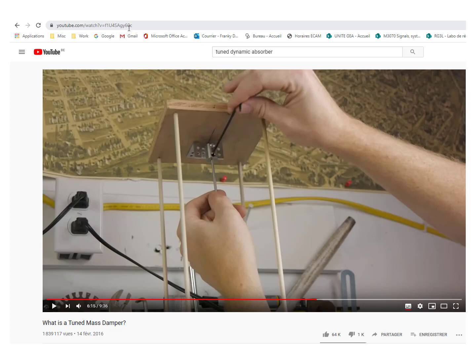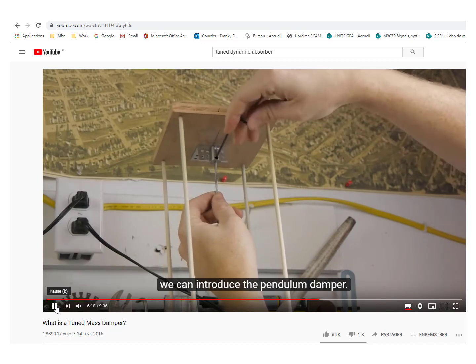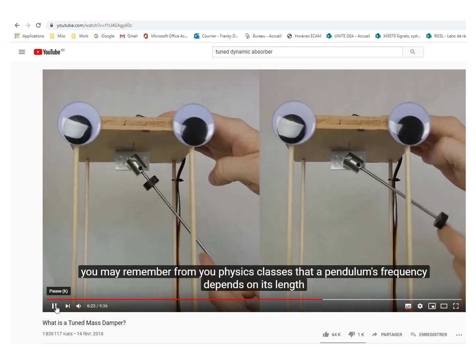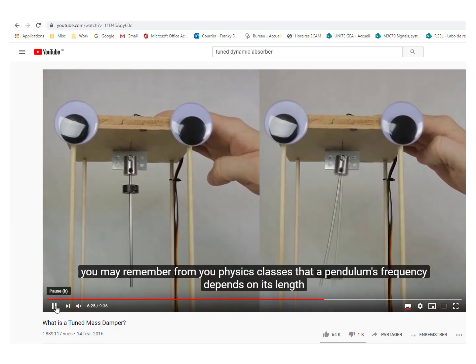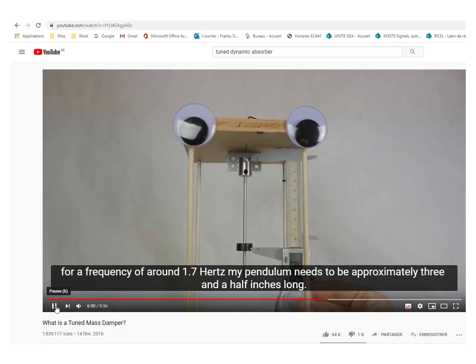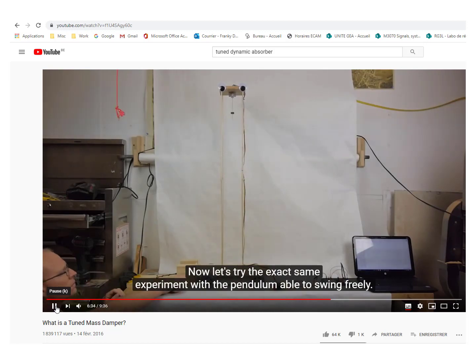And during the experiment, it is observed that this natural frequency is 1.7 Hertz. Now that we know an approximate natural frequency of the building, we can introduce the pendulum damper. You may remember from your physics classes that a pendulum's frequency depends on its length. For a frequency of around 1.7 Hertz, my pendulum needs to be approximately 3.5 inches long. Now let's try the exact same experiment with the pendulum able to swing freely.